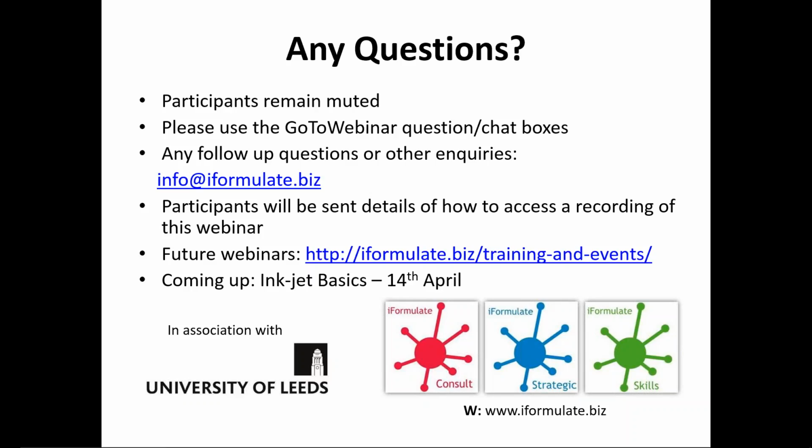That is both the energy that's required to evaporate the water, and the other factor here is that the capital depreciation over the production rate can have a big effect. So people tend to minimize the amount of moisture they put into their system if they can, in order to reduce the energy consumption, but also to get a much higher throughput for the same piece of equipment.